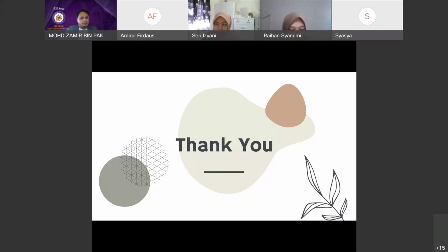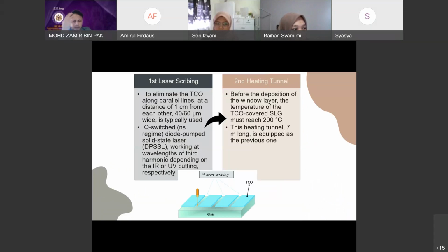Cadmium telluride is about 5 micron or so, and cadmium sulfide is typically 200 to 300 nanometer. Those two form the PN junction for the light conversion. The rest is TCO as the front contact, and then you have your rear metal contacts, buffer and so on.